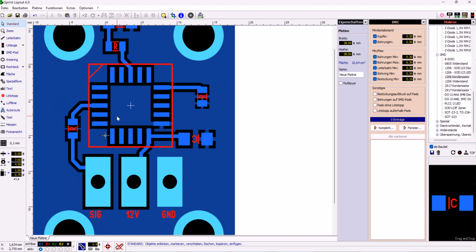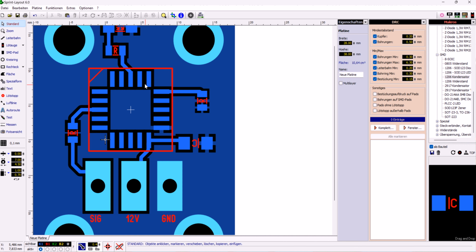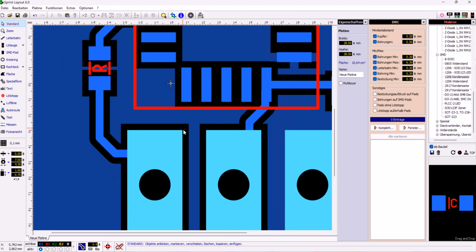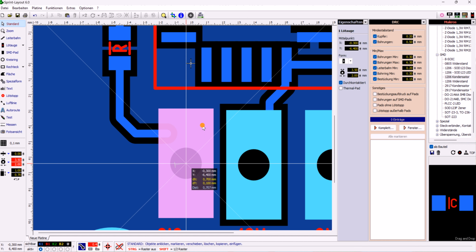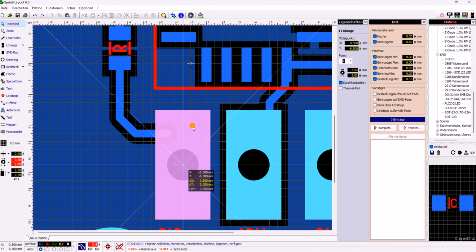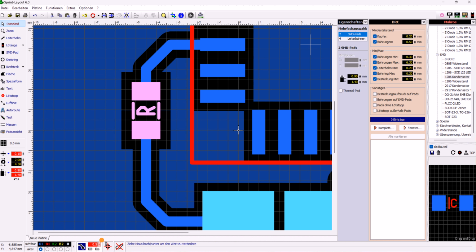The other problem, or the last one I think I have on my list, is islands. You can end up with ground islands. You don't have it in here. Actually, there's not really an island on this layout. But if we would, maybe, let's revert back to 0.5 millimeters. Let's do it like that, and also put a little more clearance here.